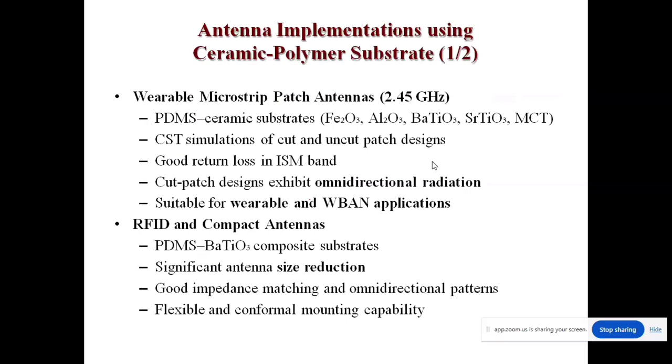So a wearable microstrip patch antenna with a polymer ceramic substrate can be based on this ceramic family, right? The CST or HFSS tool can be preferred, and we have to achieve good impedance matching at the desired frequency band. And a suitable radiation pattern we need to achieve for the desired specification. This is the wearable antenna design principle using nano materials.